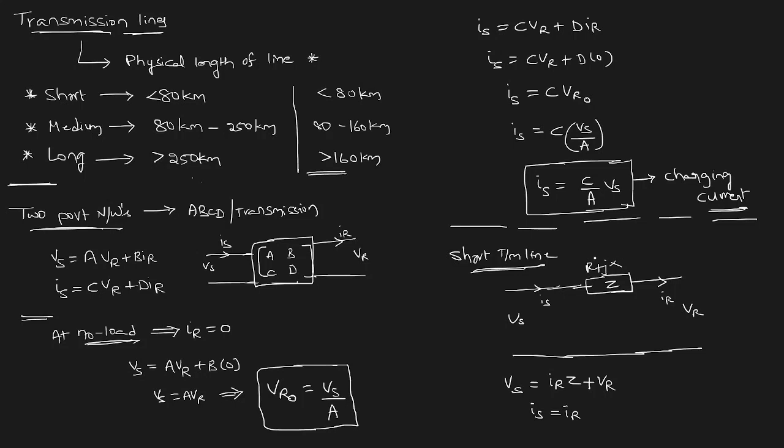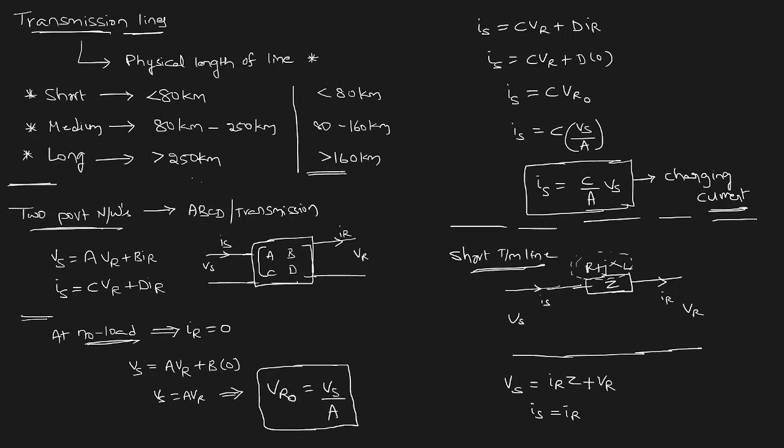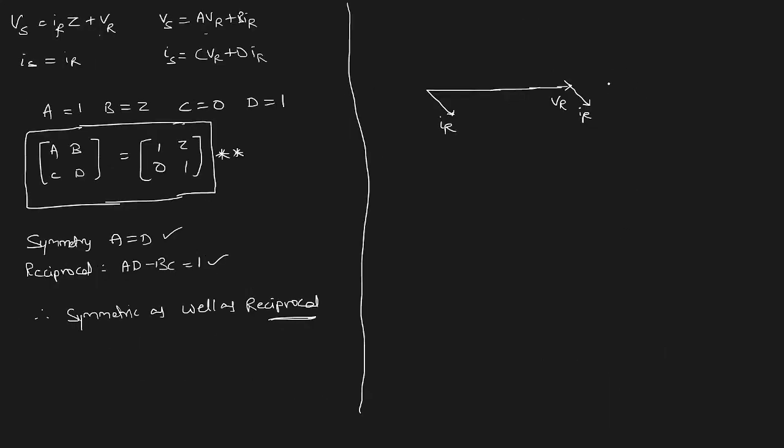Since we are using an inductive load, and the transmission line has only resistance as well as inductance, we can conclude the current will be lagging, not exactly 90 degrees, but it will be lagging. So we can use the same parallel line here also. And IR is done. Now we need IXL also. That will be at 90 degrees like this.